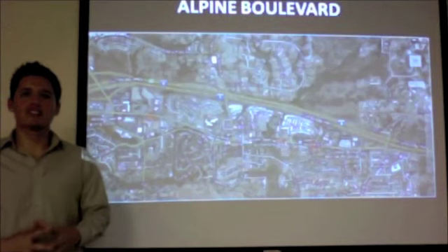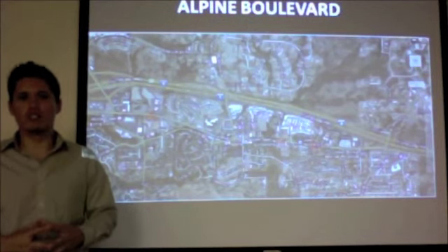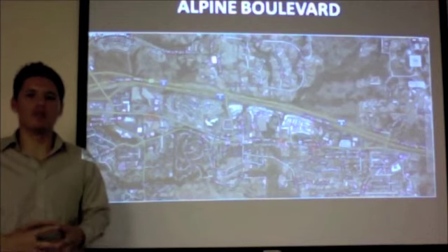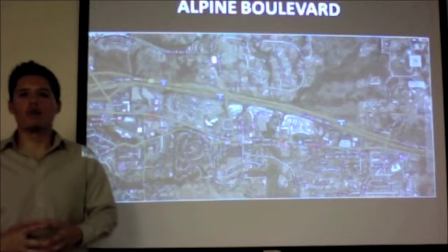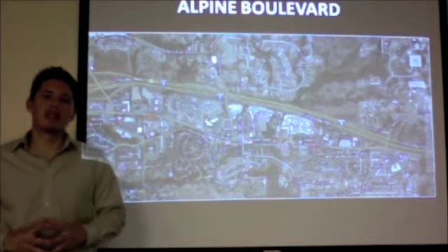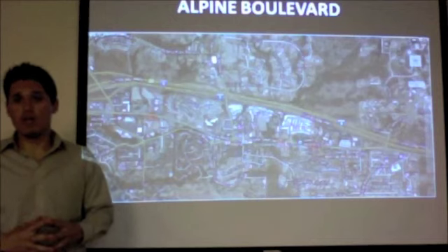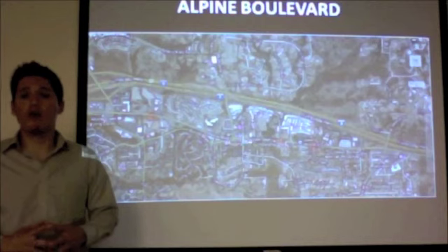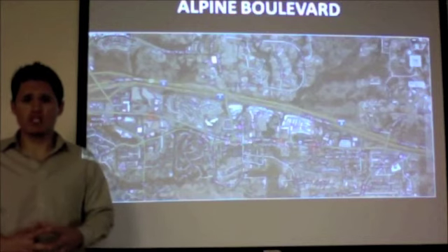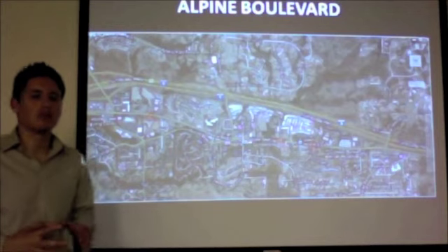The site has a continuous elevation not more than 4.5%, with elevations ranging from 1,700 feet to 2,032 feet above mean sea level. The boulevard contains existing asphalt pavement, concrete walkways, landscape areas, and grassy areas with large trees. The potential for a major erosion in the area in the short run is minimal. However, there will be check dams strategically positioned away from downstream with rock slope protection. This should be enough to mitigate any erosion problems along the boulevard.